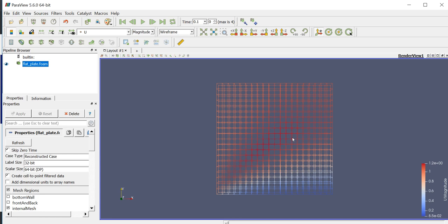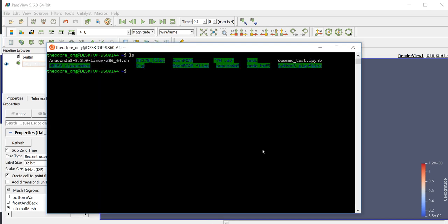That is called increasing the mesh resolution, making the resolution higher. You'll see what the effect is, and we'll find out if that is really the problem. So we're going to continue with increasing the mesh resolution, making the mesh slightly more fine.